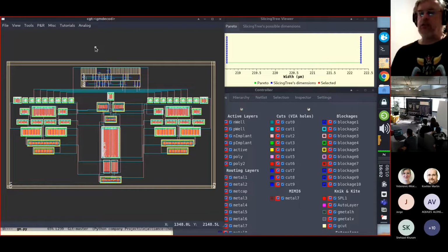The design rules I did use depend on MOSIS 180 nanometer. I think it's SCN 6M, which is a 180 nanometer technology, kind of fake one. And the sizing of the transistor has been made using a 350 nanometer technology. So from an electrical standpoint, it's complete nonsense. The sizes of the transistors are complete nonsense. Nevertheless, they are just to be changed.